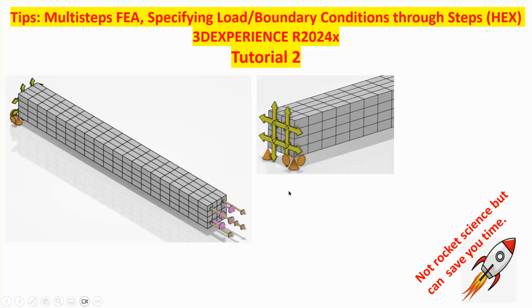And here's the situation. On the left-hand side, this bottom corner is fixed from displacement in 3 directions. That face is on a slider, which means that this can still hinge about that line. To prevent that, I just prevent the motion in the vertical direction of that corner point.